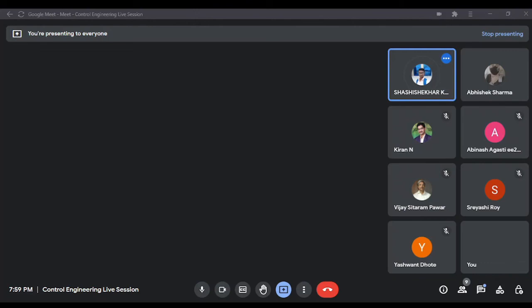Can you see this now? Yes, sir. Here you can see that the percentage overshoot is almost 82%. And the other requirement was that settling time should be less than 1 second. Here settling time is 7.8 seconds. So this satisfies neither of the requirements.